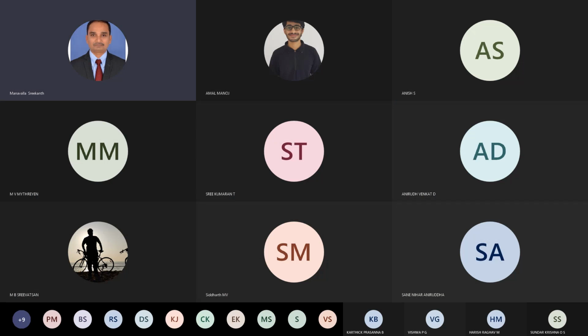Again, what questions can be asked in any lump system is just like the steady state systems. You will be asked to find out the temperature at a particular location, the heat transfer, and the temperature at a particular time. Time is playing a role because time is another independent variable in the transient system. So temperature distribution as a function of time and space is important in transient systems, also in lump systems. Okay, I will project the slides now.